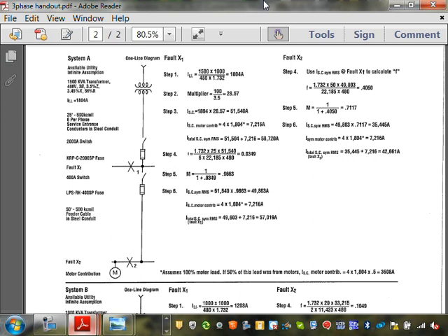How to do it by hand? These are directly from Bussmann, guys. You take the full load current of your transformer. If you look at step 1, you know how to find the full load current of a transformer: take the kVA divided by the voltage and the modifier of the three-phase. This is an 1804 amp transformer. Divide by the impedance to give you the multiplier. That's 3.5, the impedance of the transformer.